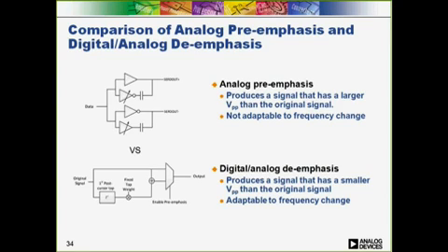Using charge injection for pre-emphasis is not adaptable to line rate frequency, so the filter must be optimized for a certain frequency range. The de-emphasis method is adaptable to a variety of frequencies.